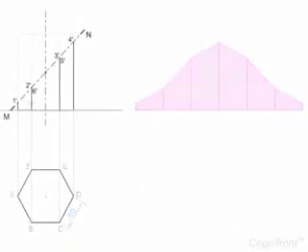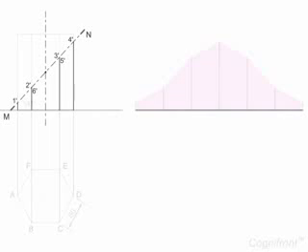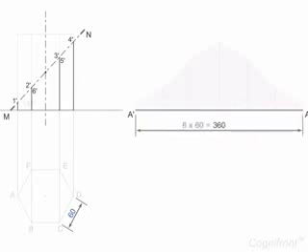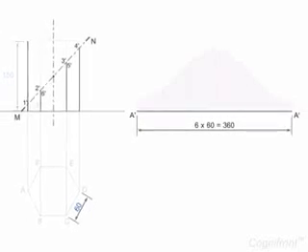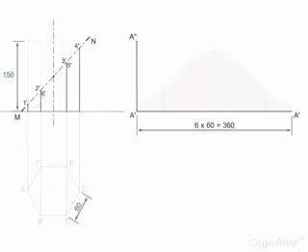To develop the surface, the prism is rolled out, making its lateral surfaces lying on a plane. The line which marks the boundaries of the rolling is known as stretch out line. It is A', here. A' has a length equal to the total side length 360 mm of the prism. Next, draw line A', of length equal to prism's height, that is 150 mm, and complete the rectangle.